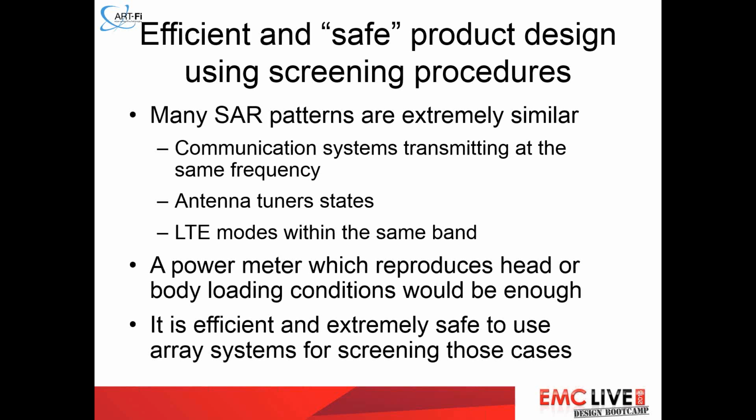And LTE modes within the same band. Here the LTE modes may have some differences in terms of currents because they excite a bandwidth that can be up to 20 megahertz, for example. They would excite slightly different frequencies, but a 20 megahertz difference doesn't make much of a SAR distribution change.